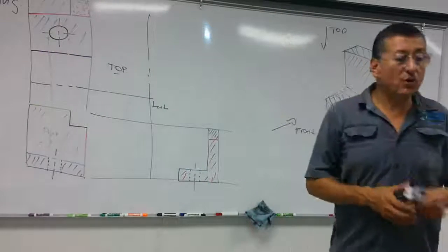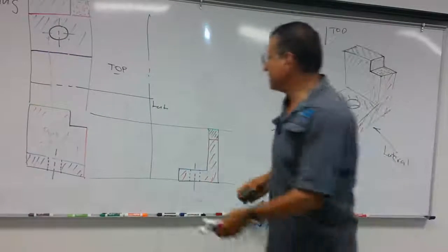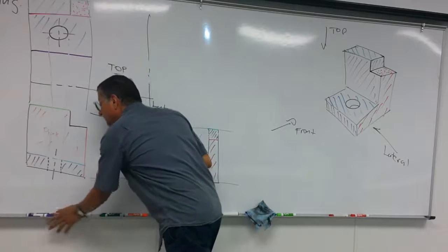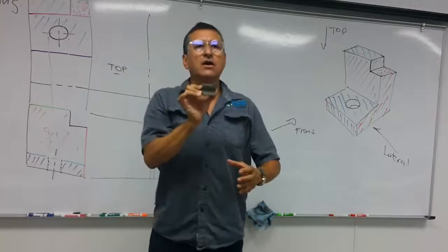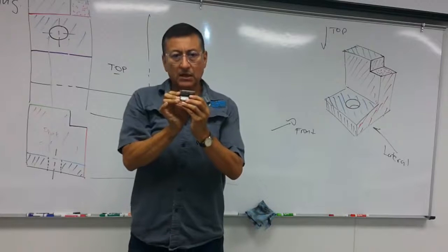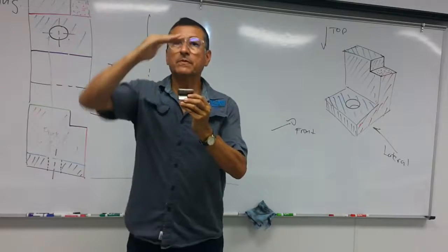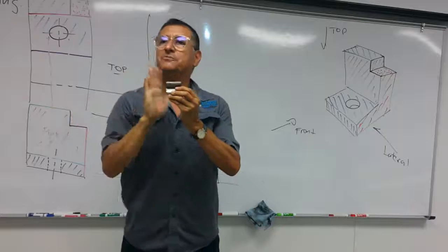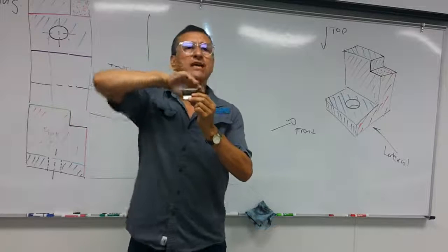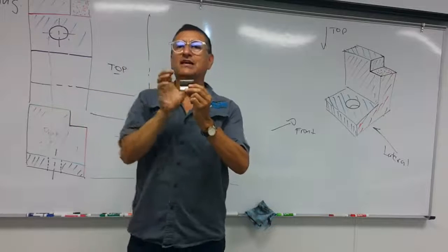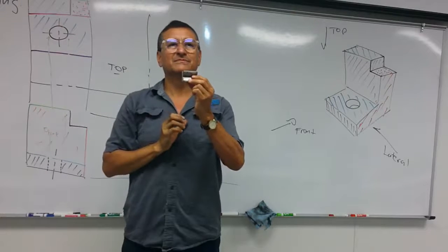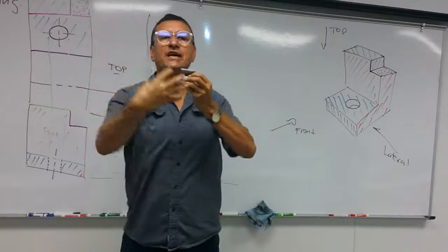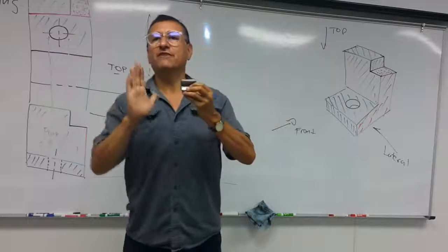It's exactly the same as if you have this object inside of a cube, no? Transparent, and you have the projections on each side of that box, a crystal box. If I disassemble the box, I have the projections on each face.